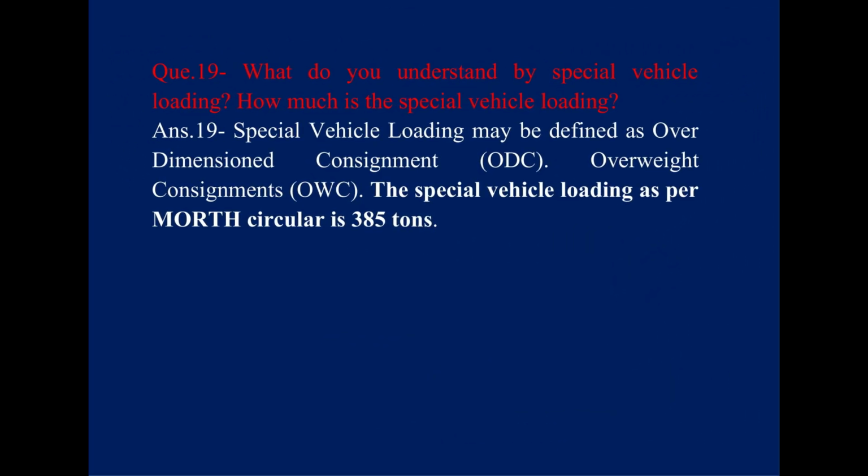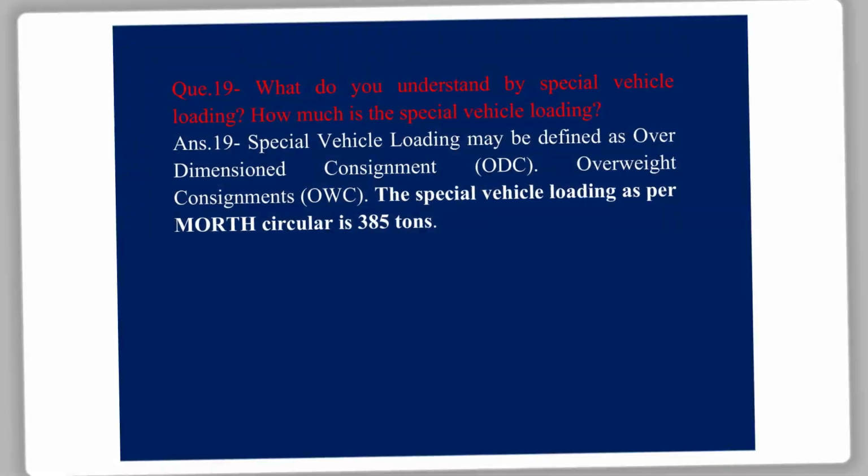Question: what do you understand by special vehicle loading? How much is the special vehicle loading? Answer: special vehicle loading may be defined as over-dimension consignment, ODC, and overweight consignments, OWC. The special vehicle loading as per MoRTH circular is 385 tons.